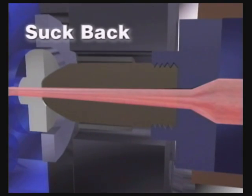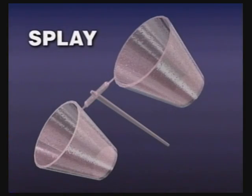After screw recovery, suckback is used to prevent the nozzle from drooling. Too much suckback may cause splay or bubbles on clear molded parts.